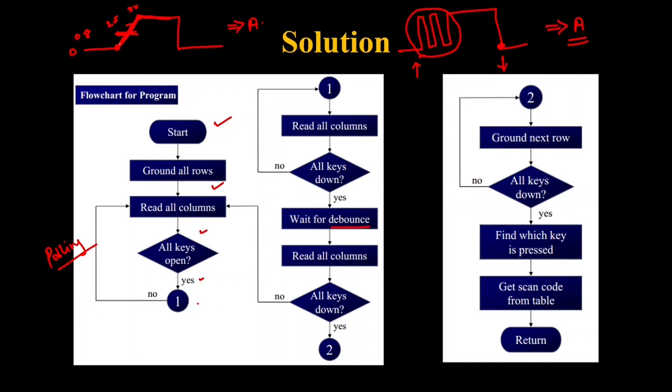So since it is crossing the values of 0 to 0.8, the value whichever I am going to get here is like no key is being pressed. And after it reaches the value of 2.5 to 5, which means the character A is being pressed. I can understand that because of this debounce condition, right?